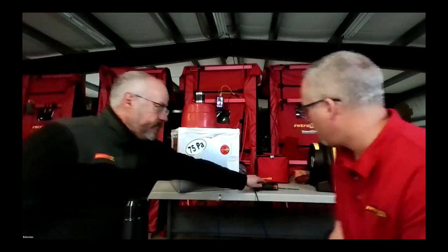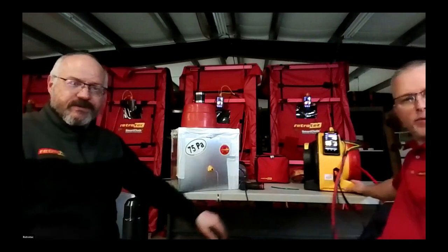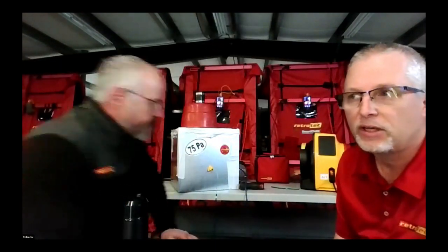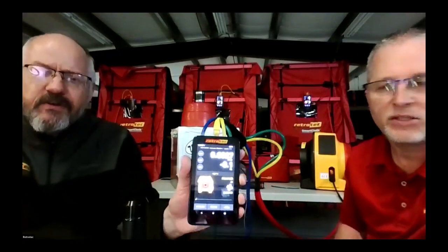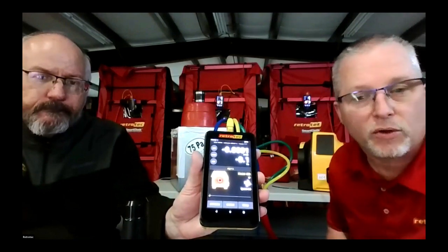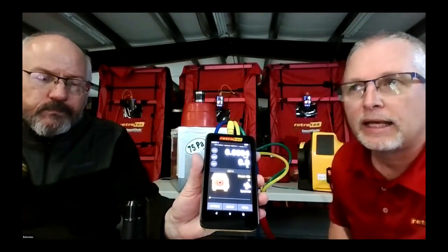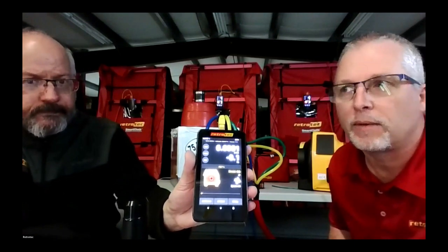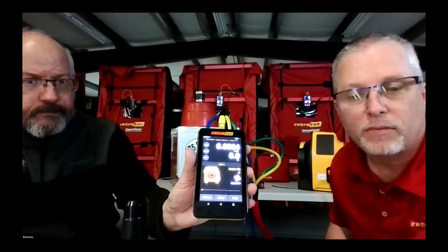Some of the other things we have would be our commercial duct tester. I don't know how familiar people are with it. It will do up to 30 inches of water column, with about 300 CFM in round numbers of flow. It doesn't change a whole lot going from 1 inch up to 30 inches. It holds its pressures all the way through. It's only 35 pounds, which is the biggest advantage over similar items in the industry.